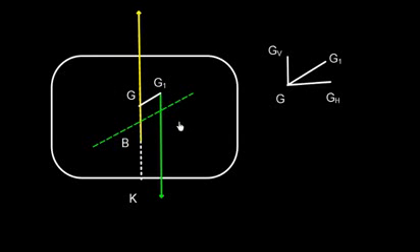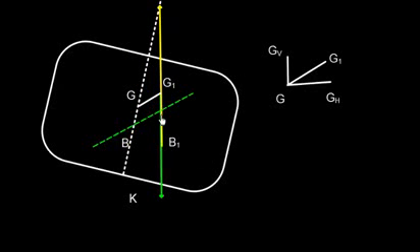Well, if it is shifted like this, this force, that is the weight force, will shift from G to G1 like this, and this will make a list movement. And because of this list movement, the vessel will start inclining in a transverse direction. So we'll have a transverse inclination, simply because the center of gravity is shifted from G to G1.